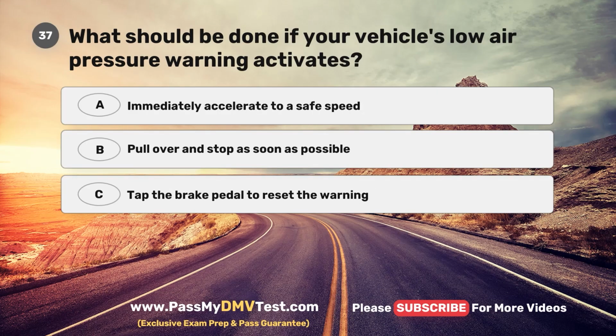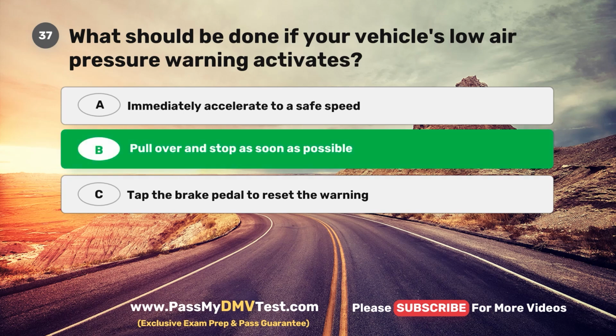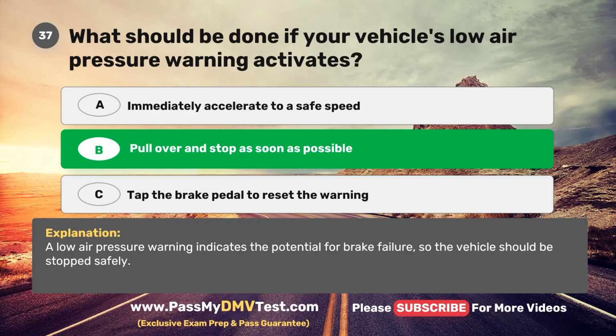Question 37. What should be done if your vehicle's low air pressure warning activates? A. Immediately accelerate to a safe speed. B. Pull over and stop as soon as possible. C. Tap the brake pedal to reset the warning. The correct answer is B. Pull over and stop as soon as possible. A low air pressure warning indicates the potential for brake failure, so the vehicle should be stopped safely.